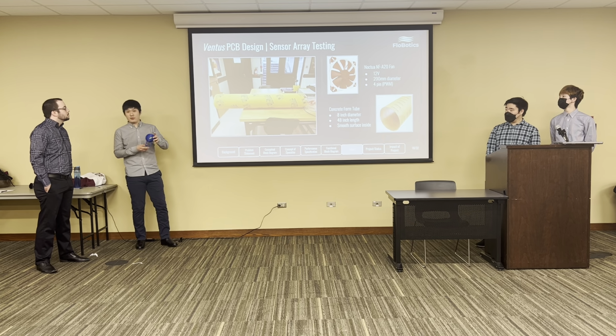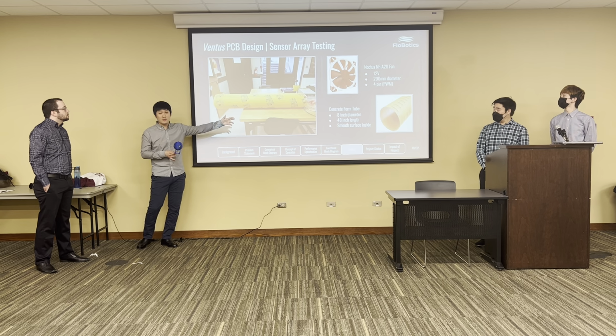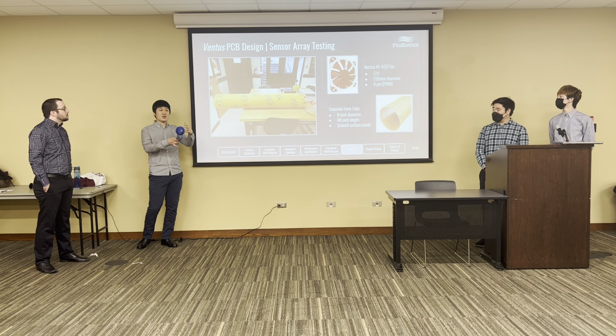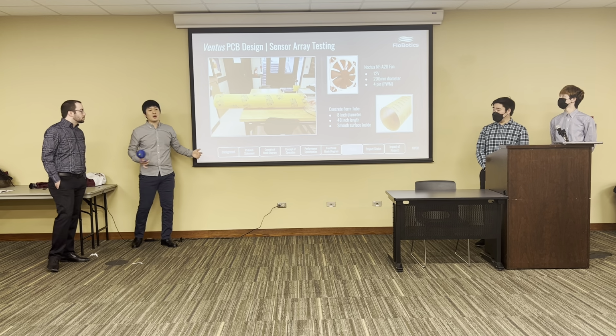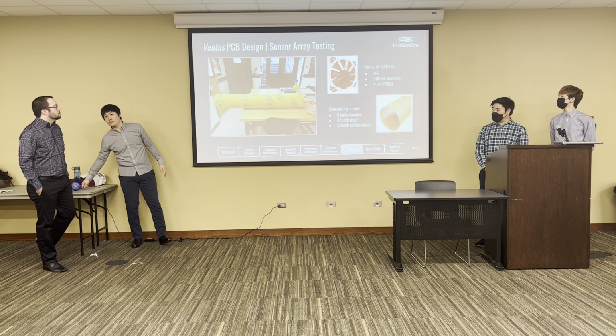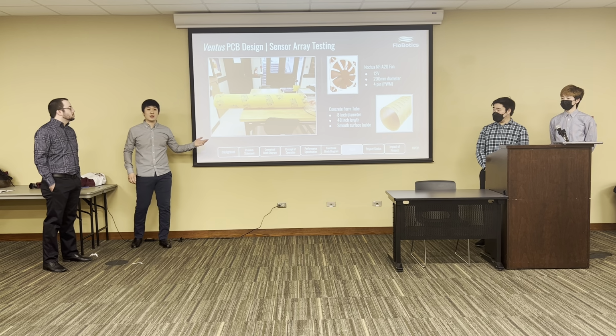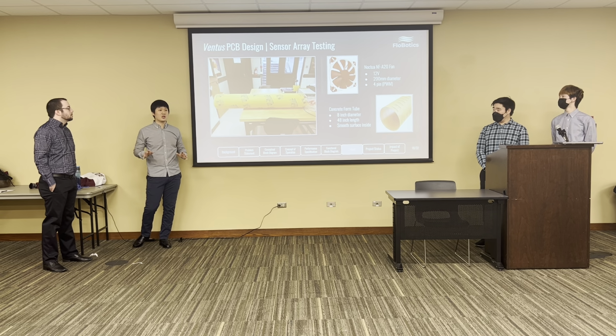Basically, we put this array inside of the tube, and then move the array like this and measure the airflow sensor, and then compare it with the commercial airflow meters, and then just calibrate it.